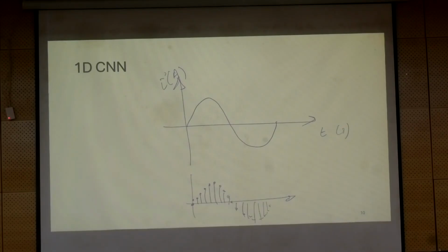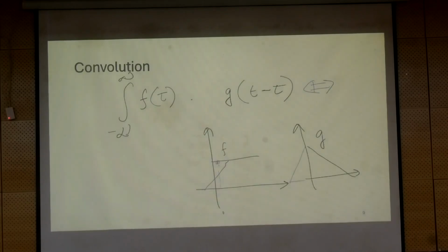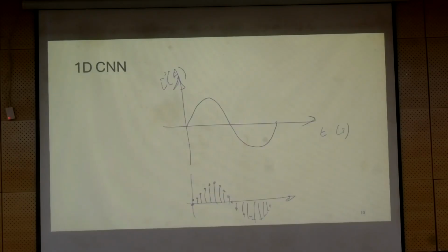All your data acquisition is converting analog to digital at a sampling rate which is high enough that you can preserve the nature of the wave shape with all the frequencies of interest. So what I want you to be aware of is this mathematical equation is useful from a continuous time signal perspective, but for all practical purposes we have to deal with the discrete time signal, because that is what we will get as a data set.